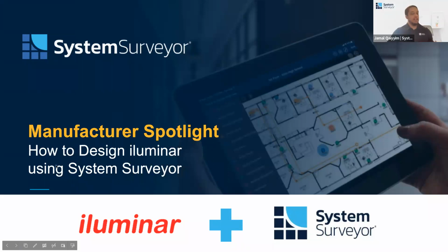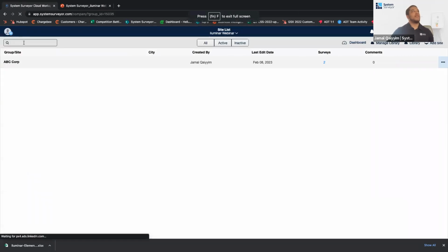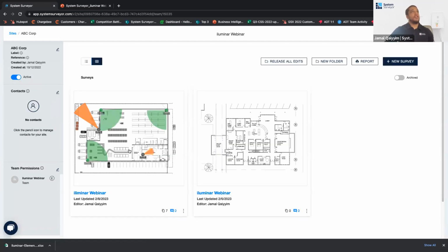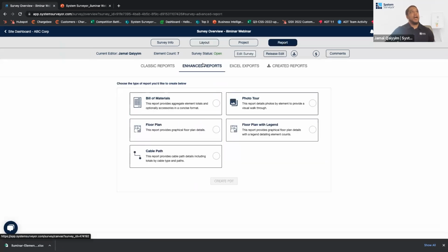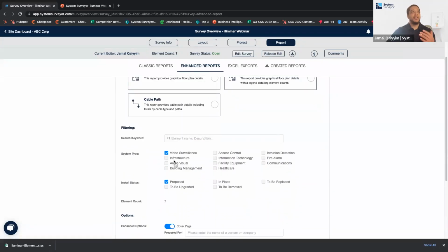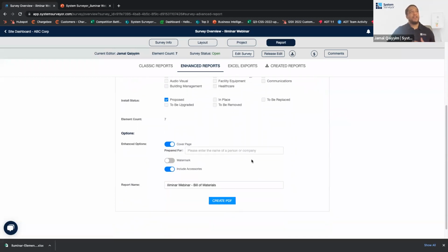So you absolutely can. And once again, I'll just hop out of this PowerPoint really quickly and go right back into System Surveyor. It's just a bit easy, but when you're in your survey that you want to create a bill of materials from, all you'll need to do is go straight into that survey. You'll go to report, and then under the enhanced reports, that's where you can select bill of materials. And it'll even give you the option to select which system types you're wanting to be on that bill of materials. And then once you have it all set, you can just hit create PDF and it'll give you a PDF of the bill of materials.